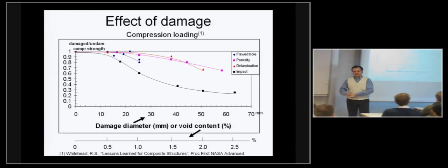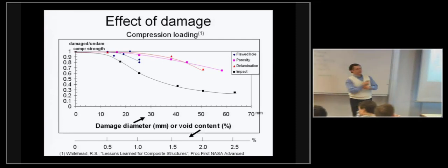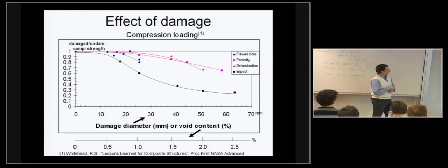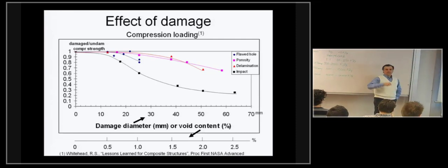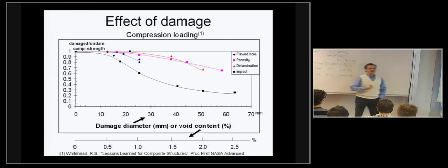So the damage on the other side, anything that you can do to the composite structure will actually affect it. You can have things like holes drilled on purpose, lightening holes or fastener holes, or by mistake because you dropped some screwdriver and it went through, or some dignitary with very spiky heels walking through the structure with very thin skins. It's happened, and it happens, and you have to design for that.